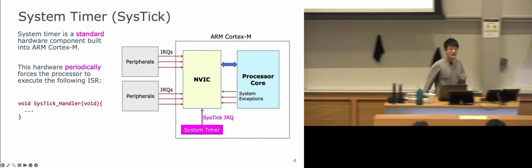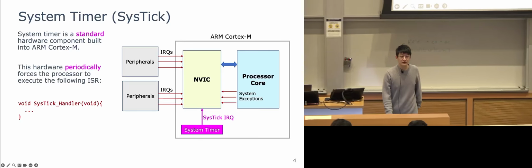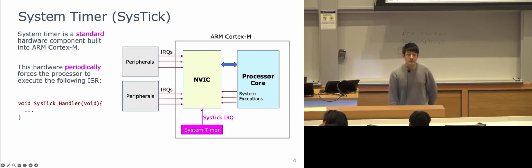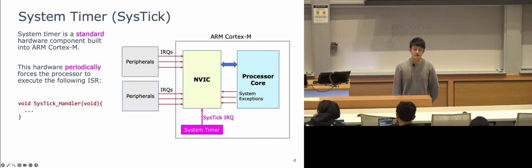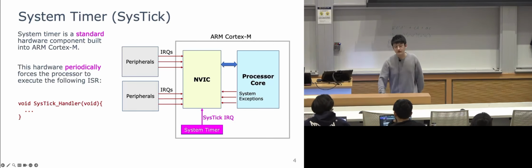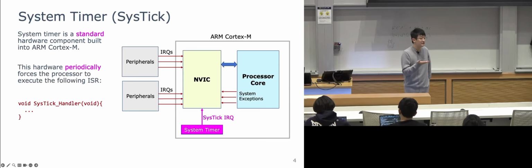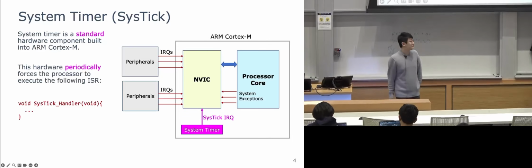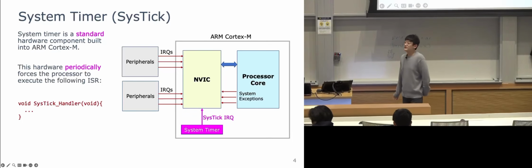Yes? What happens to the SysTick when you're setting up and you're still in the MSP mode, or if you're in the idle mode? Would it still go off every millisecond? Yeah, it will go off. It might not do anything, but it's going to keep going. Okay. That's fine. Any other questions?